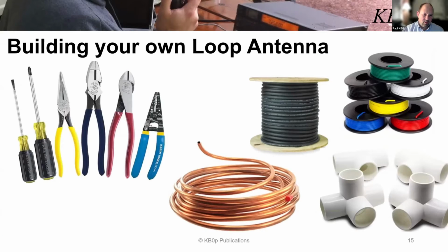But we're going to talk about building our own loop antenna. So what do we need? Well, we need some tools. We need some copper tubing, possibly wire, coax, PVC pipe. So all this stuff is locally available. You can use cable TV coax if you want. That's really cheap at hardware stores. PVC pipe is plentiful and easy to work with. Wire, we all have wire laying around. So you can actually build your own loop antenna very easily. So what I have showing next is two examples of homemade loop antennas.